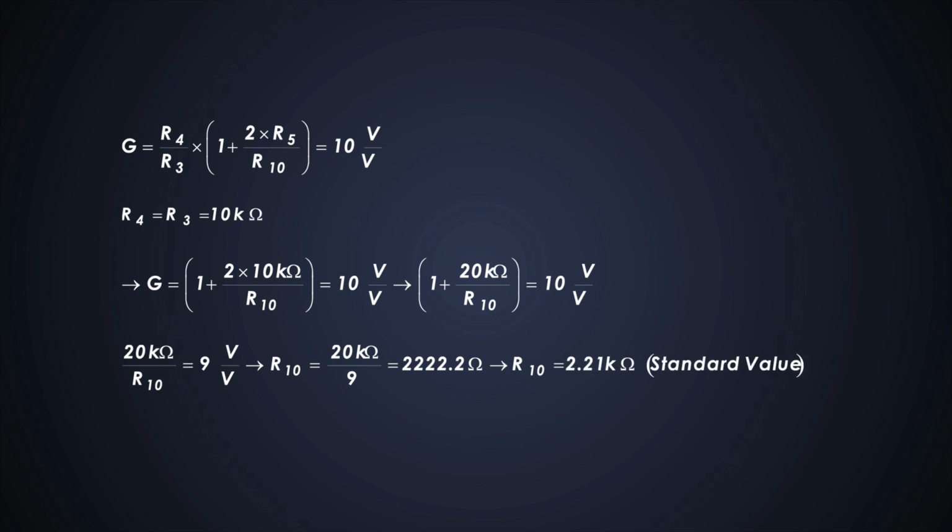For the circuit, we'll use a TLV171 op-amp. We can also simulate this circuit using software from TI. I've added the link of the simulation files in the description. This is how simply we can design an instrumentation amplifier.